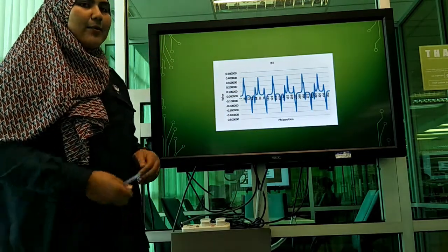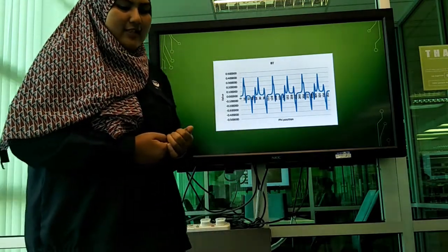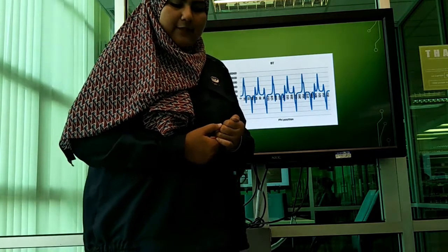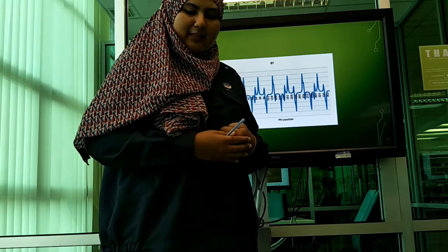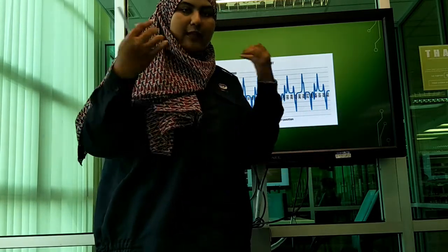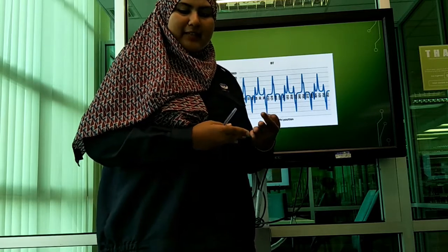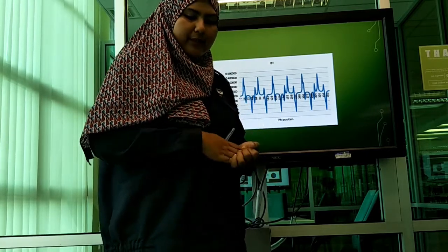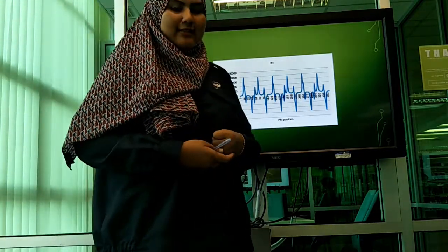Okay, next I will discuss the BT. BT is the tangential magnetic flux density. The tangential flux density has readings during transitions of the radial flux density from positive region to negative regions, and at regions immediately under the stator slot opening, it is caused by the magnetic flux lines that come out from the magnetic poles and come into the iron wall of the stator slot.